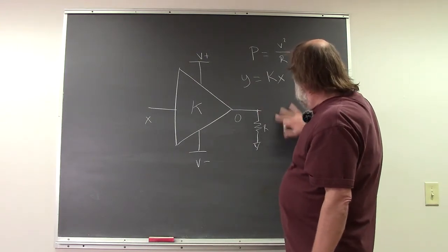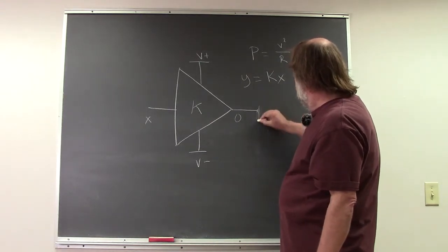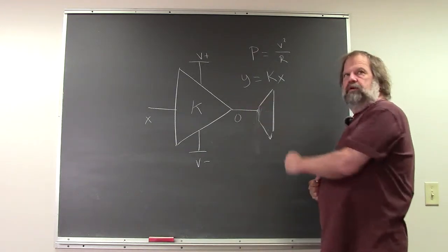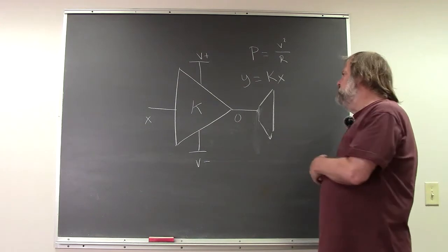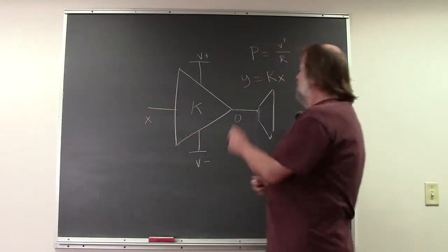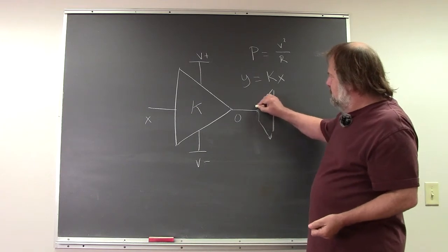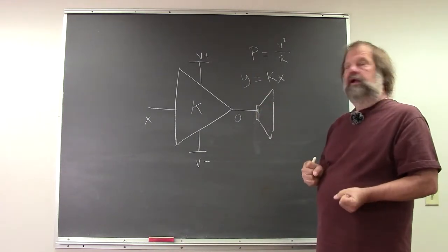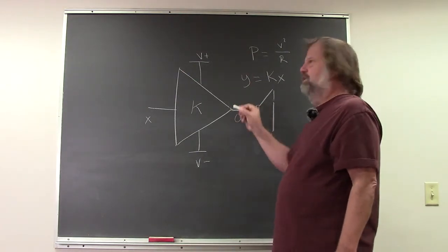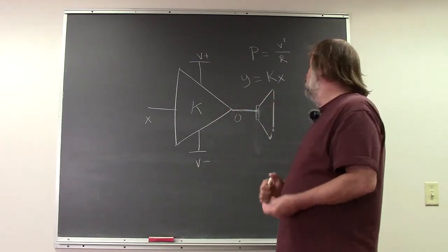So when we think about this for audio purposes, this resistor is replaced by a loudspeaker. If it's a passive loudspeaker, there'll be a crossover in front of it, and it'll be doing the full range. And if it's an active crossover, the crossover will be in front over here, and this will connect directly to the speaker. But fundamentally, we can think of this loudspeaker as being connected to the amplifier. If our speaker cables have 0 ohms, because they're also ideal, then we're going to put all of our power more or less into the loudspeaker when we can.